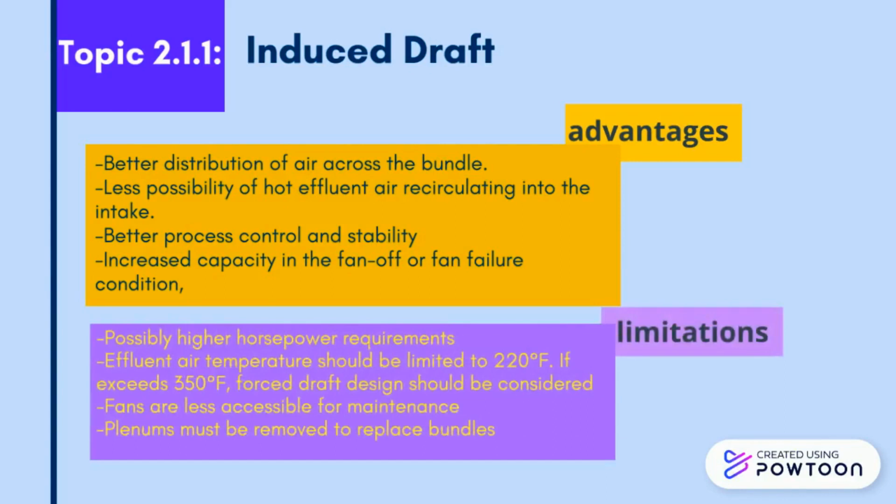Limitations: the first one is a possibly higher horsepower requirement. Second, effluent air temperature should be limited to 220 Fahrenheit. If it exceeds 350 Fahrenheit, a forced draft design should be considered. The third one, fans are less accessible for maintenance. And lastly, the plenum must be removed to replace bundles.